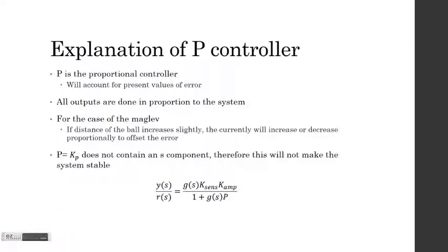The proportional term produces an output that is proportional to the current error value. A high proportional gain, in general, results in a large change in the output for a given change in the error. If the proportional gain is too high, the system can become unstable. In contrast, a small gain results in a small output response to a large input error, and a less responsive or less sensitive controller.